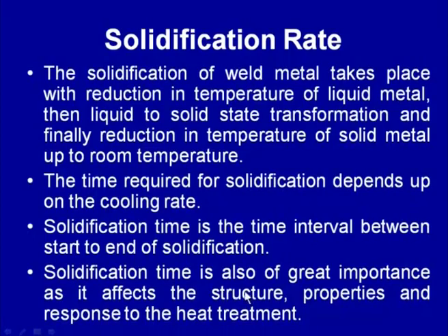We know that if the solidification time is more, then every phase during solidification will get enough time to grow to a large extent, resulting in a coarser grain structure, and so poor mechanical properties. The weld zone having a coarser grain structure will respond slowly to heat treatment, because for heat treatment mostly we require austenitizing or solutionizing.